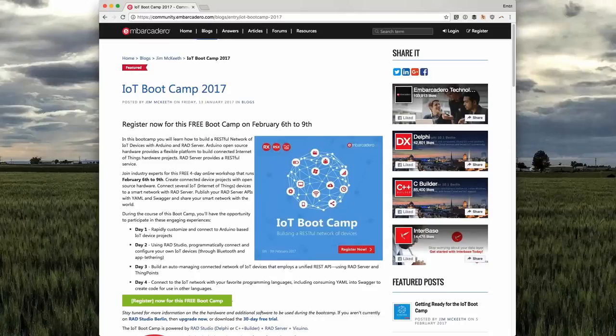So Visuino is built with Delphi, and that is your visual Arduino development IDE, right? That is correct. And so when the diagrams there where you're connecting things, that's all Visuino. And then when you hit the button, it generates code and sends it to the Arduino IDE, which comes from Arduino's website there, right? That is correct. And then the Arduino IDE actually compiles that code that was generated and sends it off onto the Arduino device or the Node MCU. That is correct.